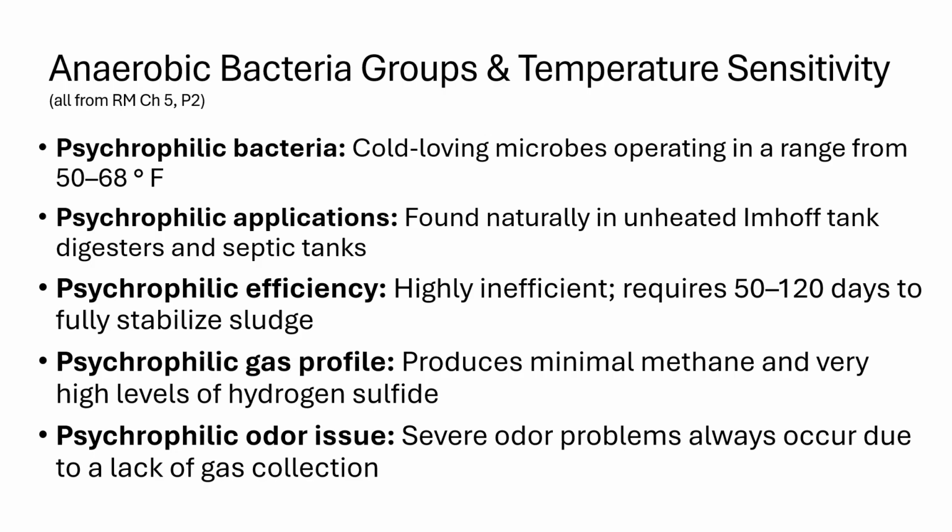So you're going to see these, like I said, in the Imhoff digesters as well as your septic tanks, more commonly in your septic tanks, because I think that's what we're all familiar with. When you go to a rural residence and you see somebody cleaning out their septic tank or getting it pumped out, and they pop that cover off, you just get that huge whiff of hydrogen sulfide. It's very odoriferous or foul smelling. So these are psychrophilic bacteria. That's where you'll see them. You really won't see them in a municipal wastewater treatment plant.